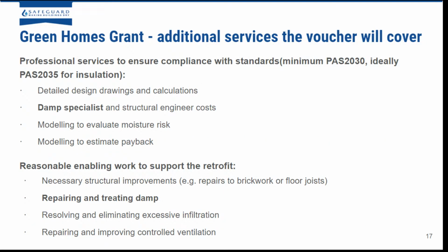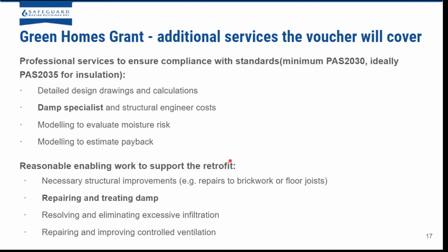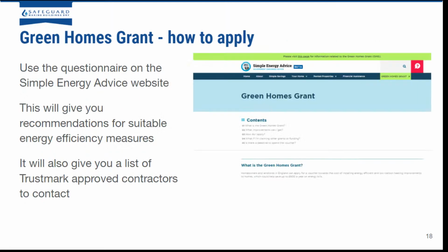So the Green Homes Grant comes with additional services that the voucher will cover following PAS 2035 and really focusing on this whole house approach. One of the things it will cover is a damp specialist, as well as repairing and treating damp, which is reasonable enabling work to support the retrofit. So it's really looking at that concept of bringing the property into good repair before installing your energy retrofit measures.